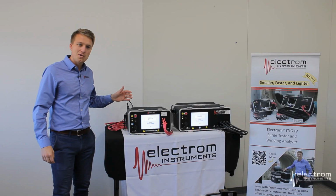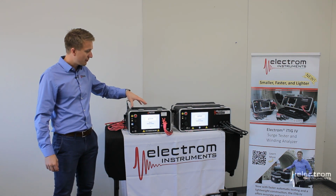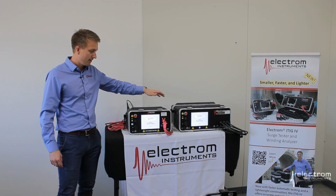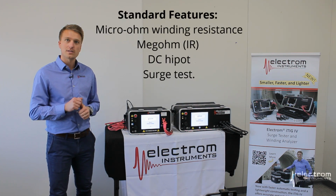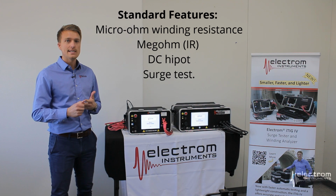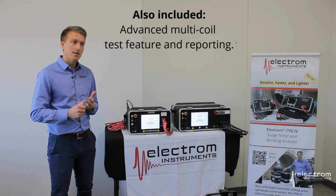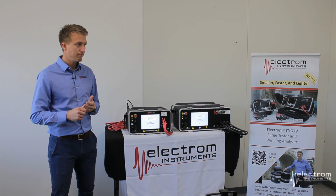This is the iTIG 4 Model D. The Model D comes in two different sizes, the 4 kV and the 6, 12 and 15 kV. The D model includes micro-ohm winding resistance, Megohm or insulation resistance, DC Hipot, and the surge test. Also included is the advanced multi-coil test feature and reporting.